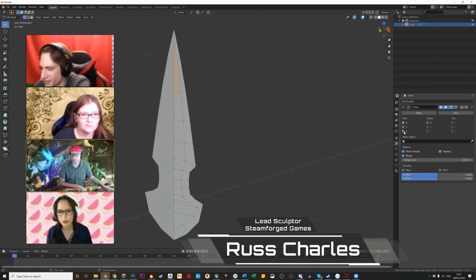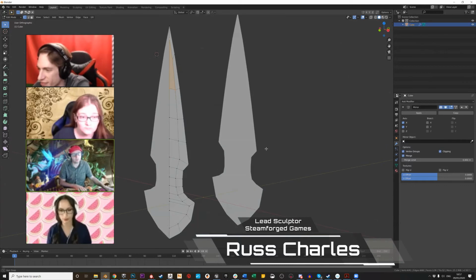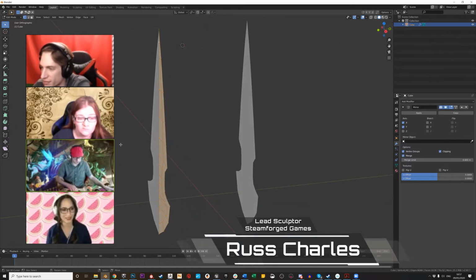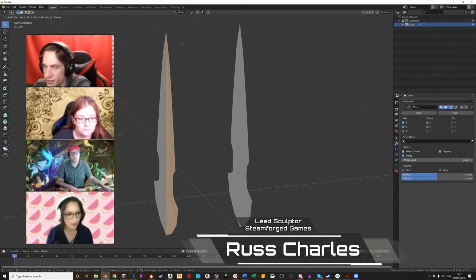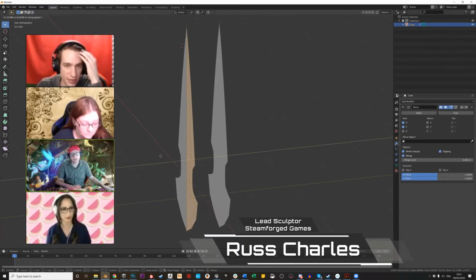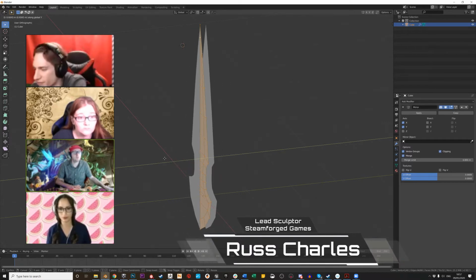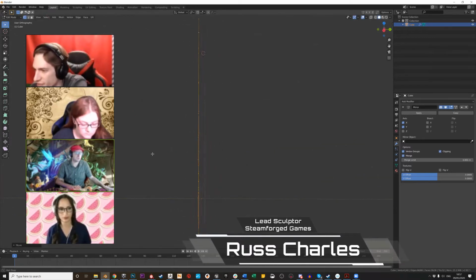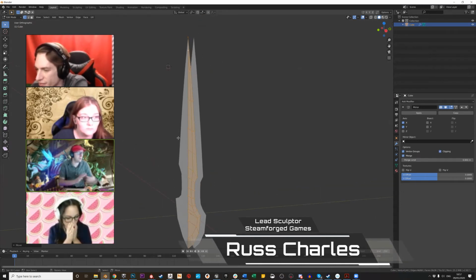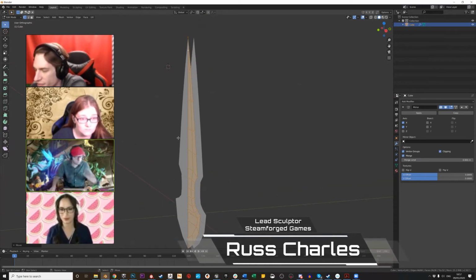So first things first, turn on the Y-axis in my mirror modifier. Hit A to select all of your vertices. Hit G to be able to move the object, and then press Y so it's moving on the Y-axis, and you can only move it forwards and backwards. And then just move it till it's sort of about there, really. I mean, we're doing this a bit by eye. We could be doing this with really precise measurements, but for this first walkthrough, it's easy enough to do it by eye.